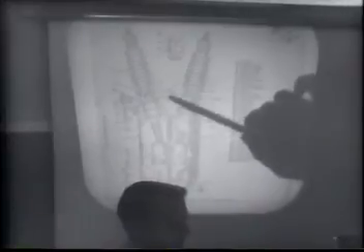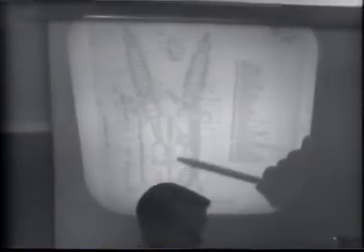Other types of circuit breakers would use different media here. We have circuit breakers in which some of the insulation in here is compressed air. Compressed air has a much higher insulating value than normal air. Another type of media there is sulfur hexafluoride, which has a much higher dielectric strength than plain air. Some of the other components that are used here, this operating rod here that moves the contact open is made out of plastic or wood in some cases.